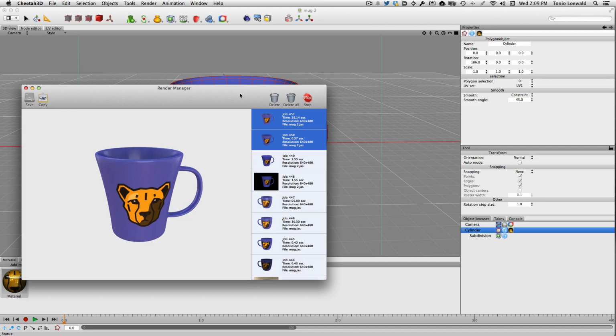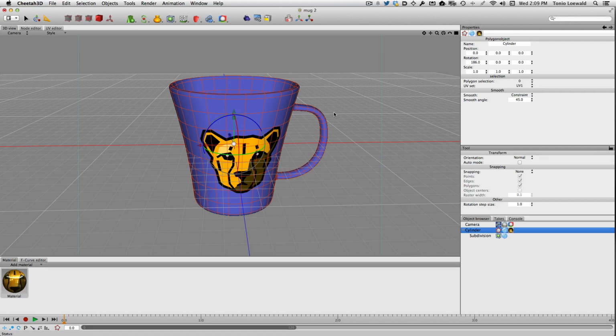So let's summarize what we've done here. We started off by creating a basic mesh, and then we refined that mesh. We started off with a bowl, and then we added the handle, and we joined the two by importing the handle into the parent and throwing away the original handle, and then bridging it to join the two. Then we refined that mesh by using bevel and ring cut to improve its shape.